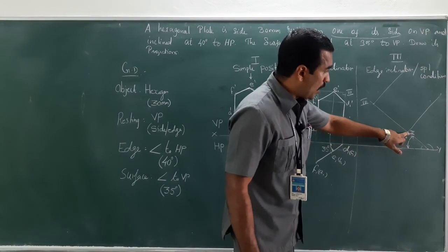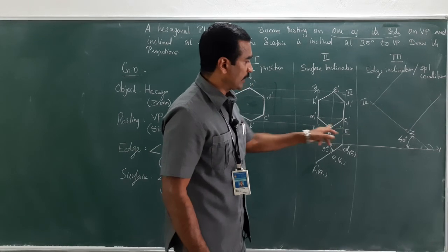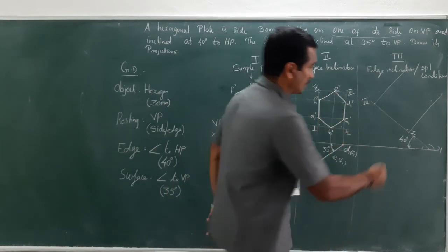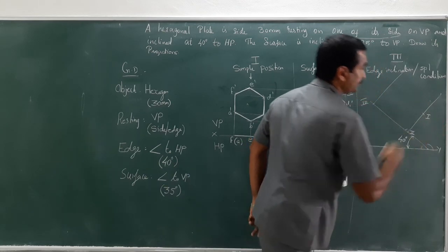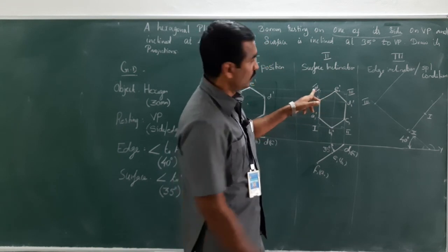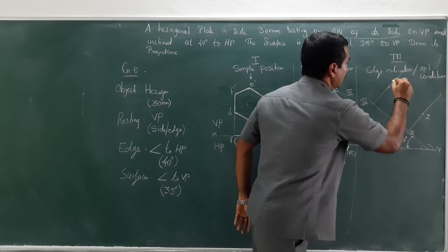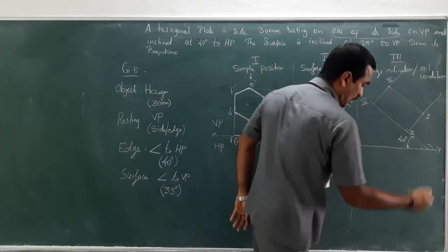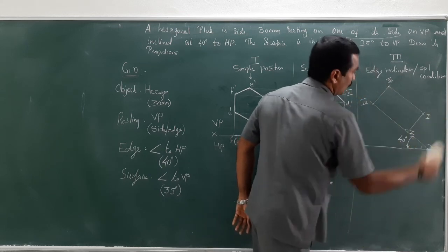See, look at point 2, which is 90 degree, and opposite of 2, point 1 is there. So, measure the distance between 1 and 2 in your compass, and cut an arc. This is 1. Then opposite of 3, point 4. Measure the distance between 3 and 4 and cut an arc. This is point number 3. Now, connect it. So, now the box has been tilted at an angle of 40 degree.